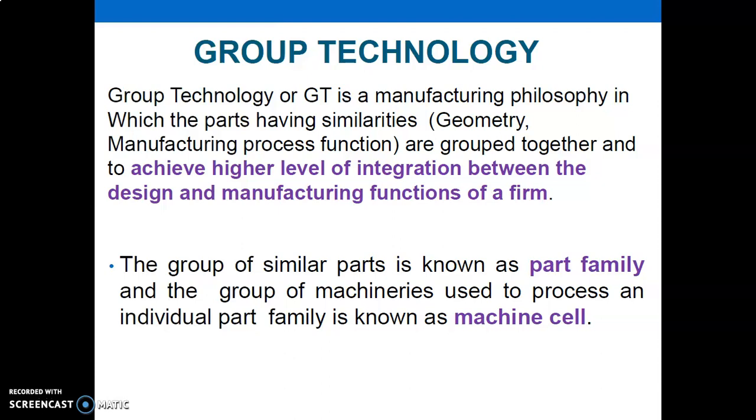But what we are doing here, we first initially identify the machining steps. Suppose we have shafts with different diameters and in different steps. Even some shafts have a keyway, or some shafts may have oil grooves. So it's a different thing, but the main physical shape is common.